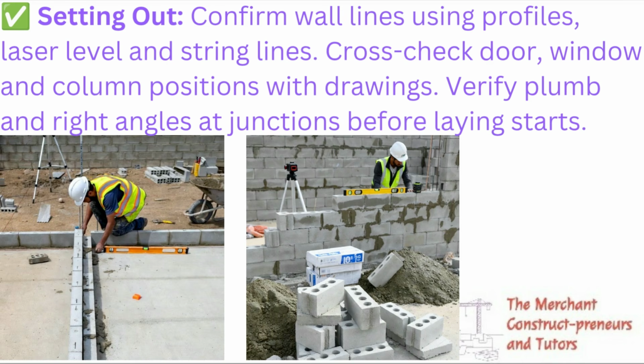If not, you will just be laying blocks and at the end you have to start removing them. Also ensure that these ones you are setting out, the blocks are vertical and at right angle, because that is where the problem will start from. Once the blocks are not properly aligned, problem will start from there.